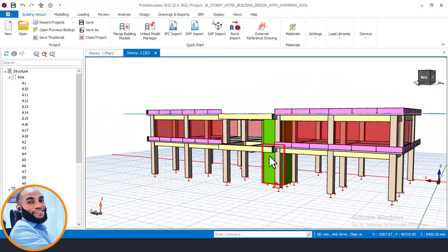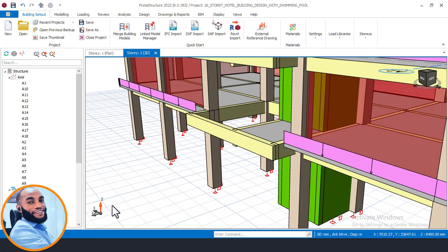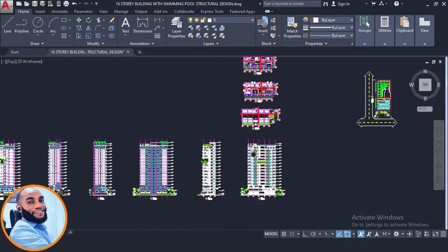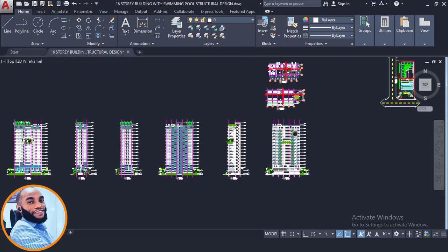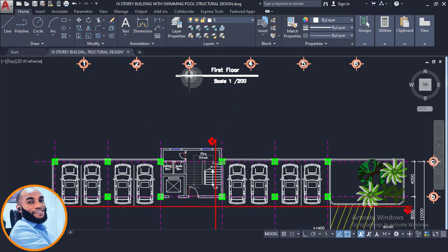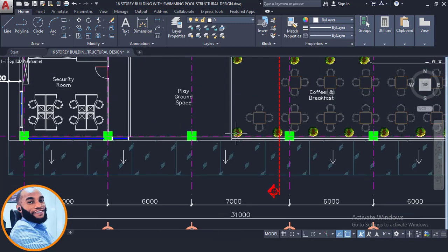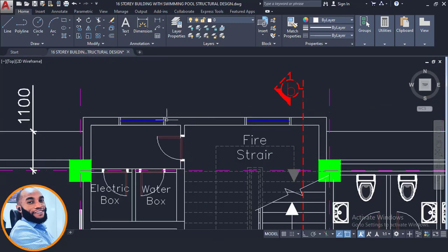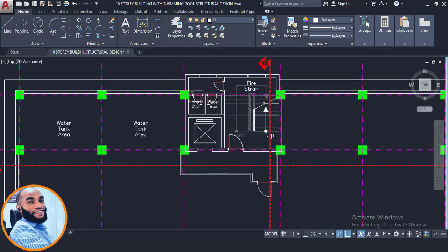Okay, so let's now confirm from our CAD file if this one here has a wall load or not. This is the area on the CAD file. That's a back view. This place we are seeing here is the back view, and for what I'm seeing right now, there's a window here. So since there's a window, there's a wall load around this place, and also that continues. Let me check again. Yes, it all has windows, so there should be a block wall around that area, around the cantilever beam area.